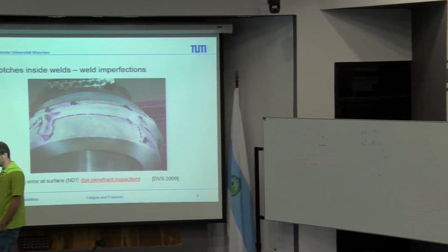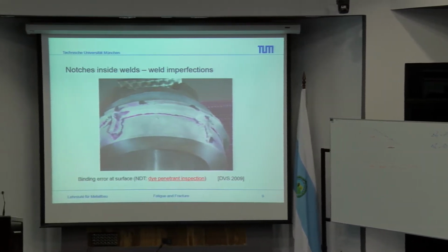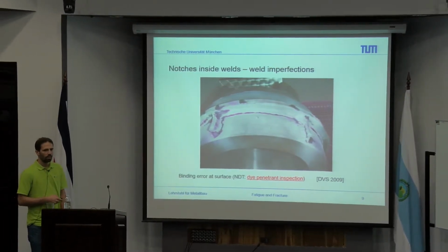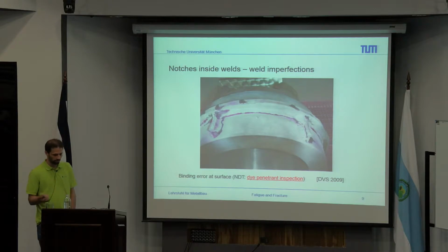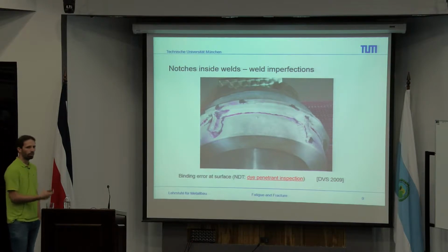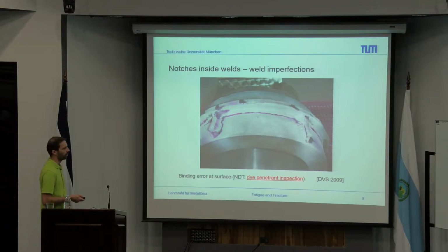You can easily see this by dye penetration inspection. This is just a color you spray on, and in the end you see how proper the connection at the surface is.